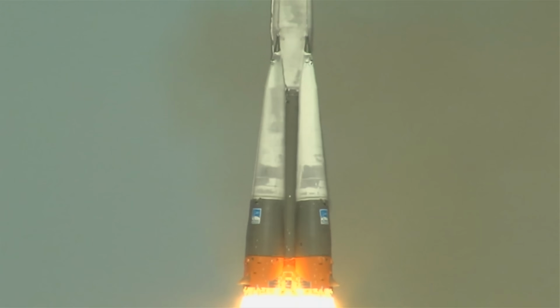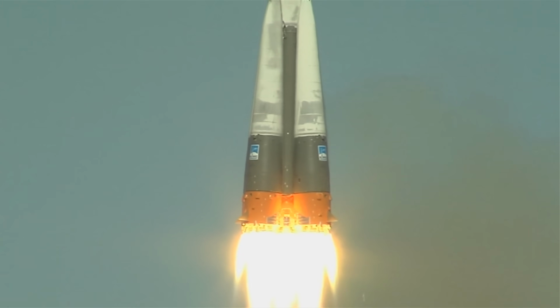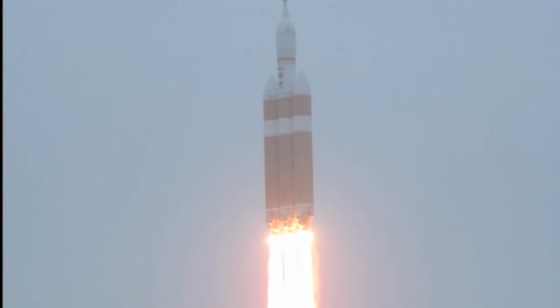Some good examples of gas generator open cycle engines are the Merlin 1D engines on SpaceX's Falcon 9, the F1 and J2 engines on the Saturn V, the RD-107A and RD-108A as we mentioned on the Soyuz, the RS-68 on the Delta IV Heavy, and many, many others. It's easily one of the most common cycle types for orbital rockets, being extremely effective, highly capable, and relatively easy to develop compared to other more exotic cycle types.